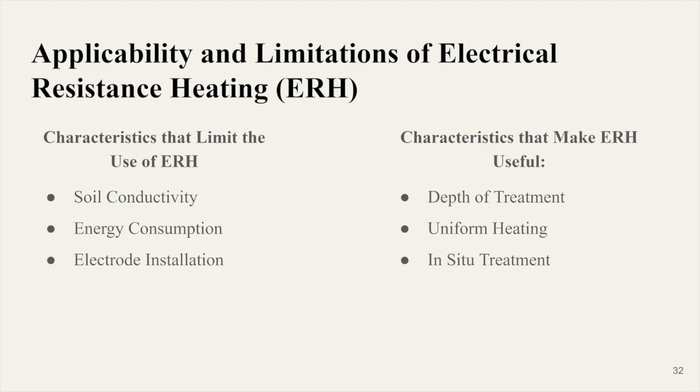ERH is effective for treating contaminations at various depths within the subsurface, including shallow and deep contamination zones, which is very similar to the TCH method. Uniform heating. ERH can achieve relatively uniform heating at the subsurface, ensuring thorough treatment and improved remediation efficiency.